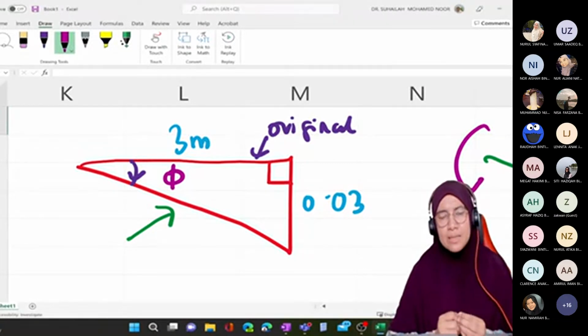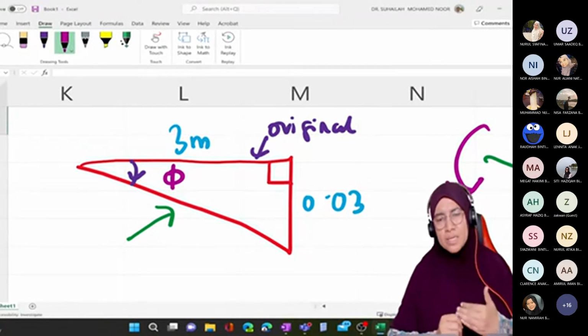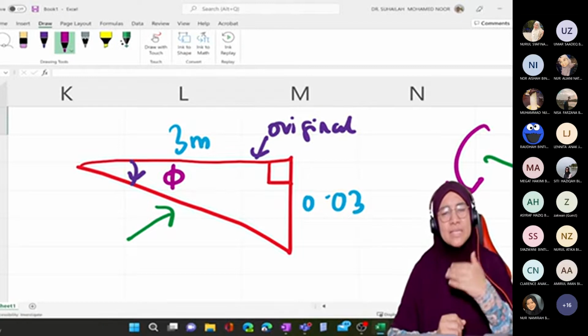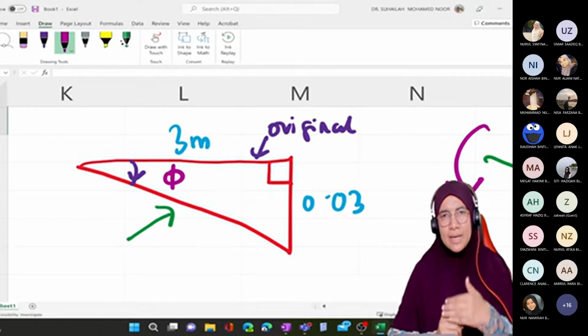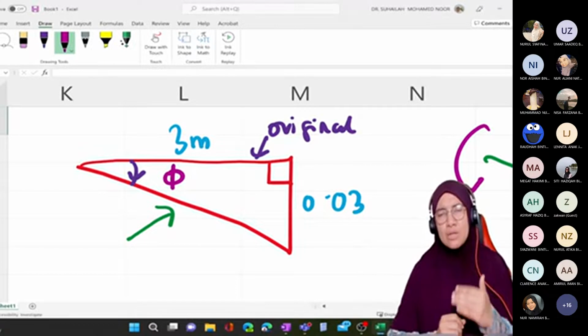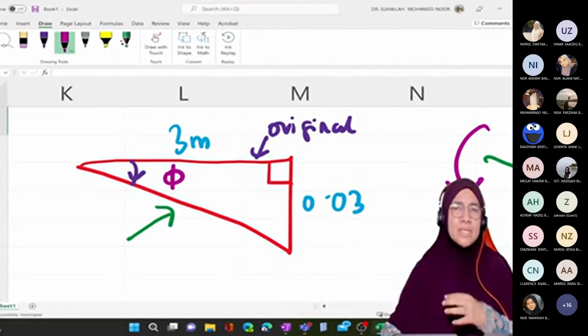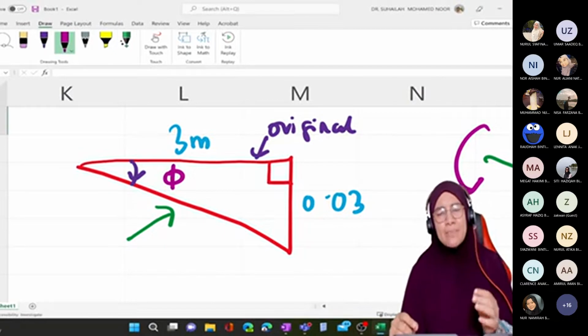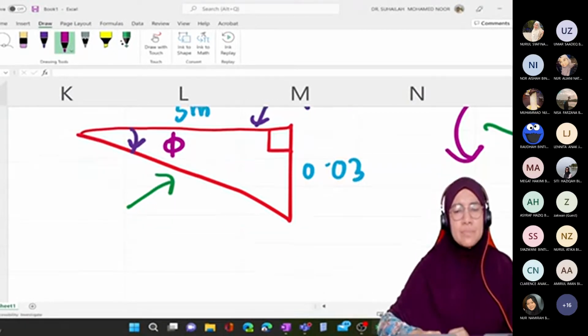The angle from original position to new position after settlement. If the angle is clockwise, FEM is counterclockwise. Between chord rotation and FEM, it must be opposite.